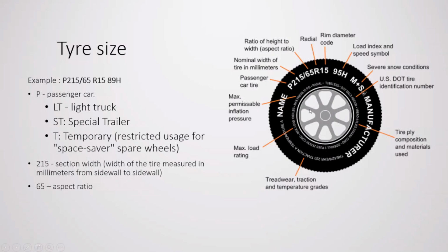Suppose you need to change your tires and the rim just to improve the ground clearance or just to lower the ground clearance. Both things happen. But it is not recommended to change the tire sizes and rim sizes, because it mainly affects vehicle stability, especially fuel consumption, and also the torque variations.